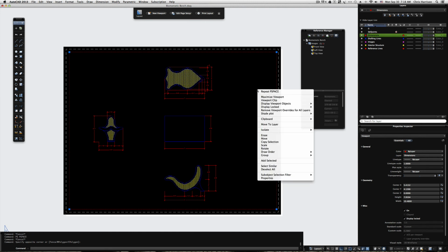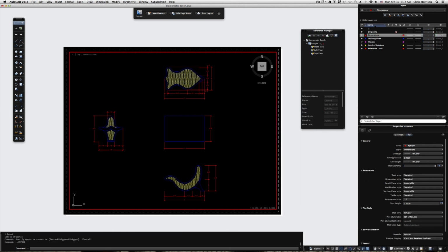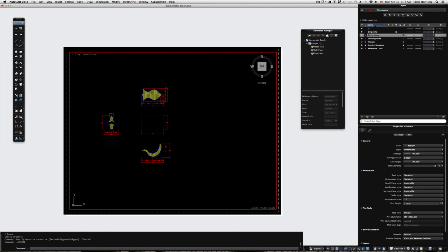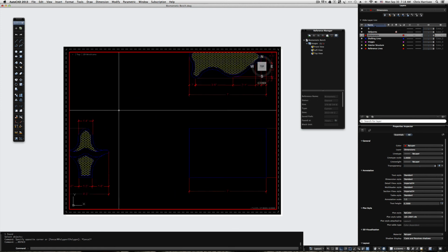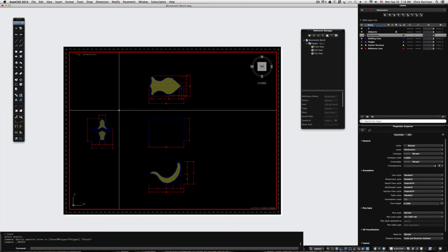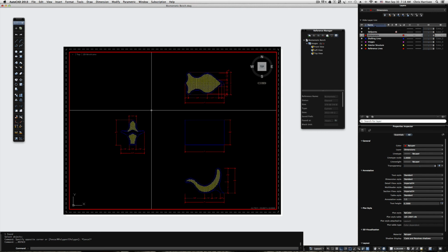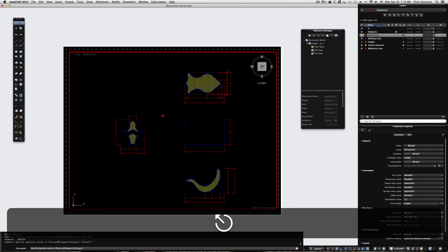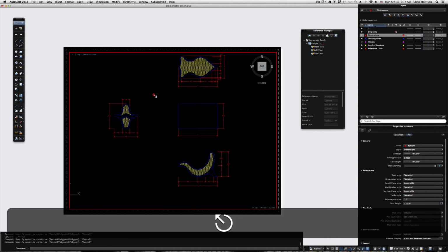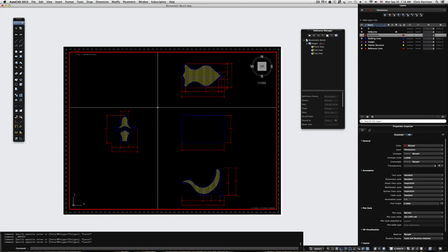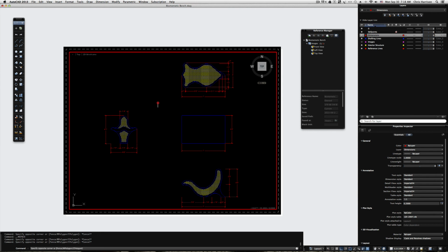I'm just going to select the viewport, right click, and display locked, and no. So if I double click on this, now it's like I've opened the window and I'm manipulating the drawings that I've created in model space. So I can zoom in and out. You just want to find a zoom and an area that you're still in your print boundary. Again, you can scale in here, but we're not doing that in this particular exercise, because we're going to change the shape when we put them into our board anyway. I just want to make sure they're going to be a decent size so that we can see them.